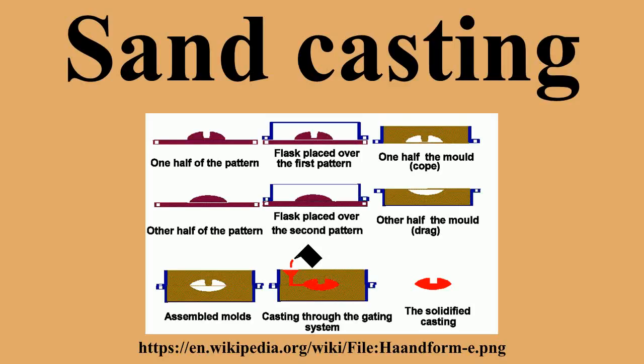Horizontal sand flask molding. In the first automatic horizontal flask lines, the sand was shot or slung down on the pattern in a flask and squeezed with hydraulic pressure of up to 140 bars. The subsequent mold handling, including turnover, assembling, and pushing out on a conveyor, was accomplished either manually or automatically. In the late 50s, hydraulically powered pistons and multi-piston systems were used for the sand compaction in the flasks. This method produced much more stable and accurate molds than was possible manually and pneumatically.